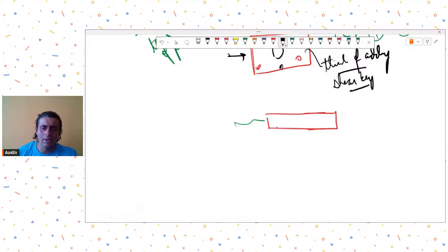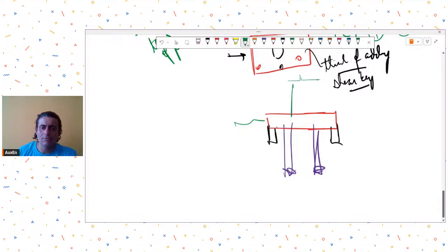But then you can think of integrating some sort of shear cap like this. Okay, and these are your piles, let's say. So this shear cap will help you to take some amount of lateral load. So not shear cap, shear key. The shear key will help you to take some sort of lateral load. Again, that will depend on your